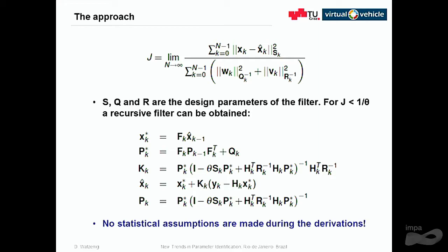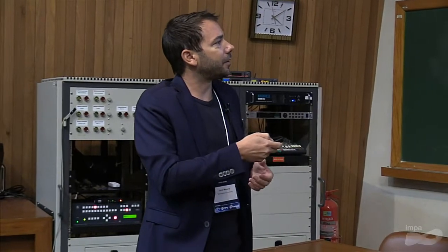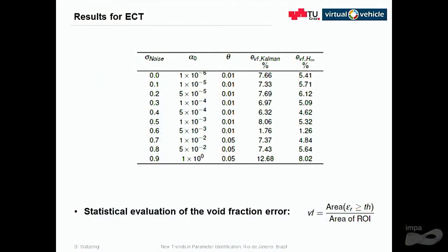Basically, it's an optimal filter like the Kalman filter, but with the big benefit that you can deal with the system matrix and its process-dependent noise within the system dynamic matrix, so A plus delta A. Exactly, and that's just the way to reduce to the Kalman filter.